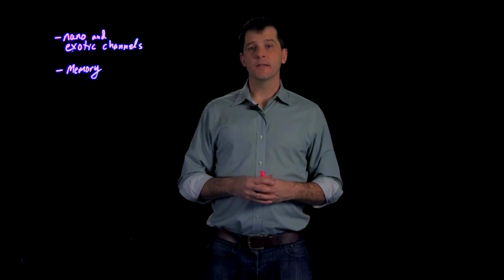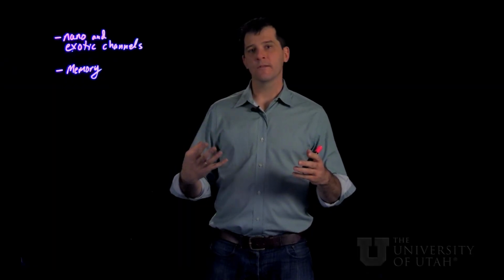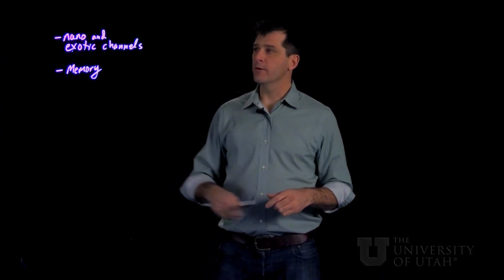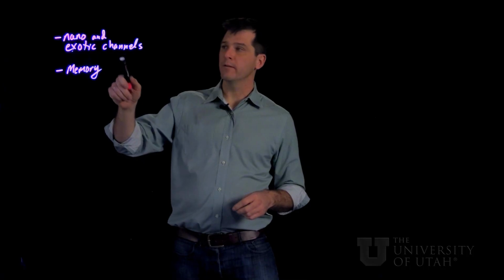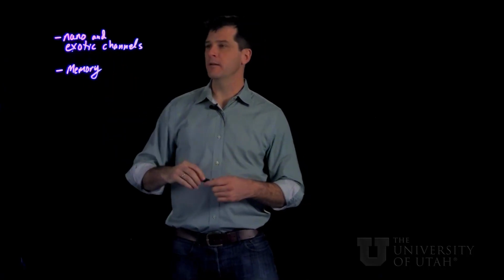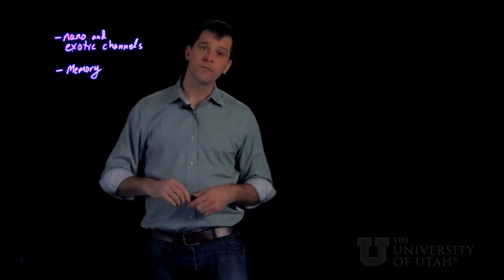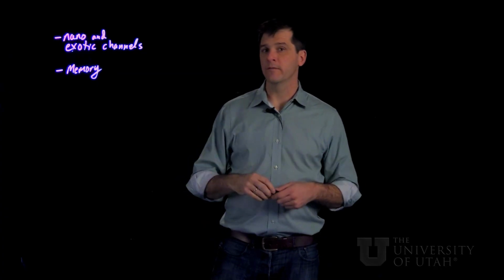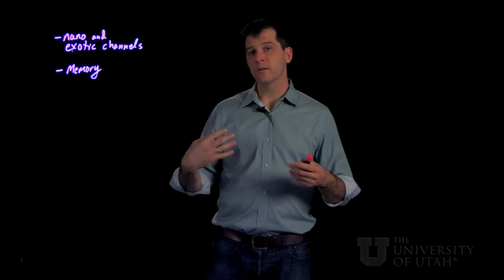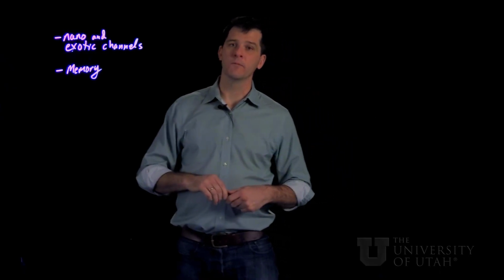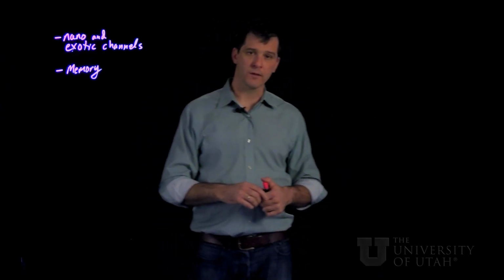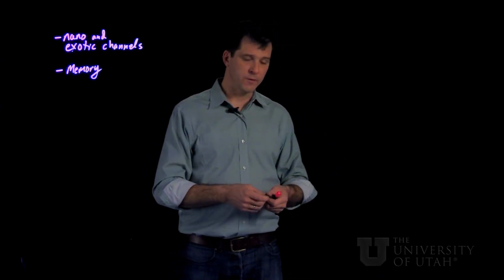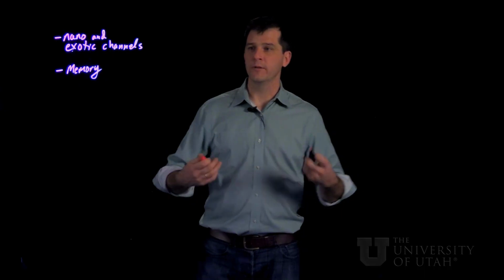Okay, in this short little section, we're going to look at modifications to the traditional silicon MOSFET structure. First, we can talk about using other materials and nano objects in the channel. And then second, we can talk about how to turn the MOSFET into an element of memory. And this is critical for the NAND flash memory that's dominating the market these days for solid-state hard drives as well as little thumb drives, USB drives.